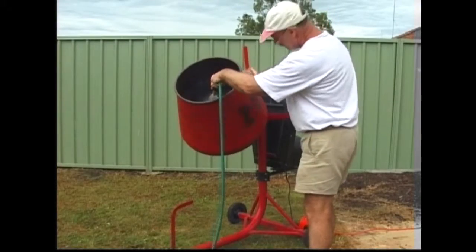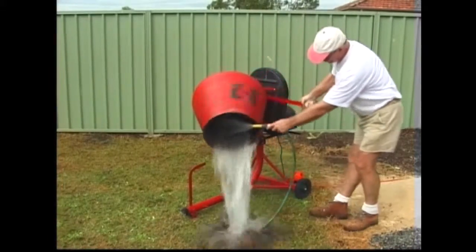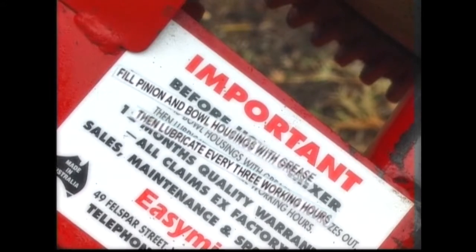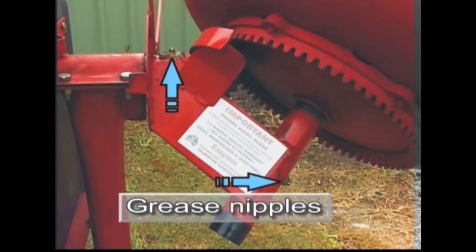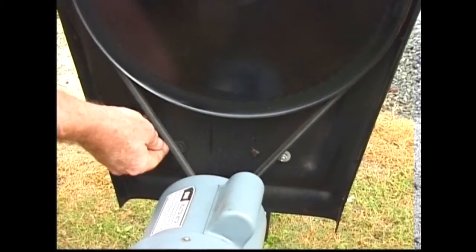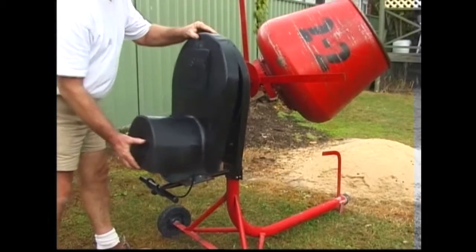Routine maintenance ensures a long serviceable life for the mixer. Prompt cleanup of leftover slurry in the barrel is an important aspect of this maintenance. Wiping bare metal parts with a film of oil prevents rust build-up between jobs. Manufacturers' recommendations regarding regular greasing should be followed. Regular maintenance should also include checking the drive belt tension. A loose or slack belt will cause slipping and loss of power under load.